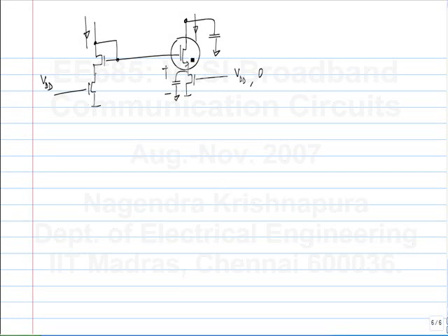Okay. So if you use the same transistors as before, for the main current mirror, you will have VDSAT plus the voltage drop. But what happens to that voltage drop? Is it going to be different if I switch at the drain or the source? Why? It will be the same. The gate source voltage is different. So actually it is going to be different. Okay.